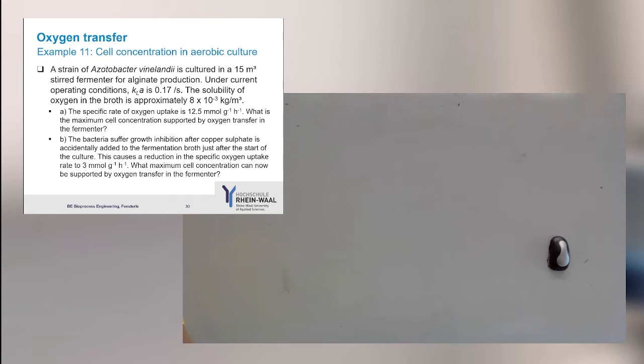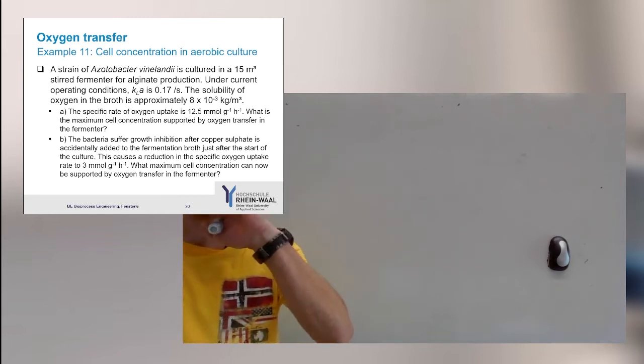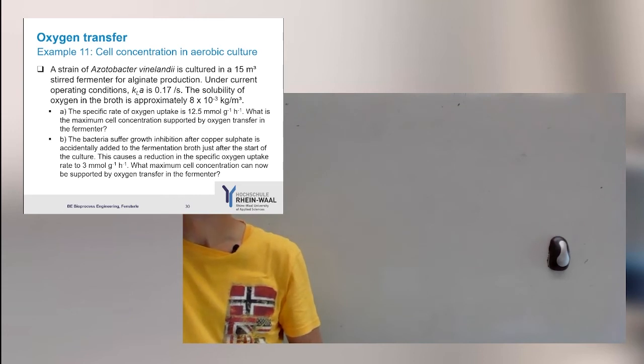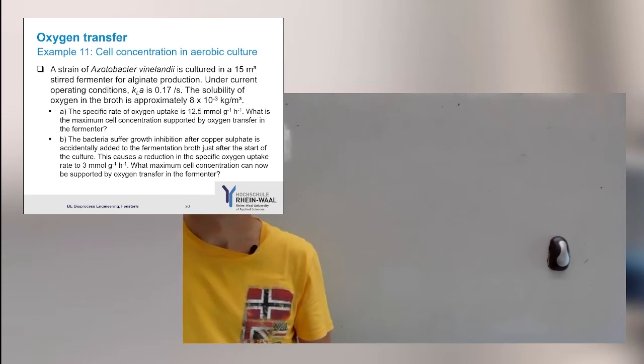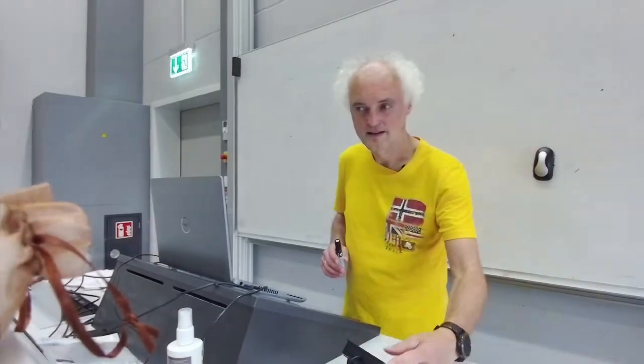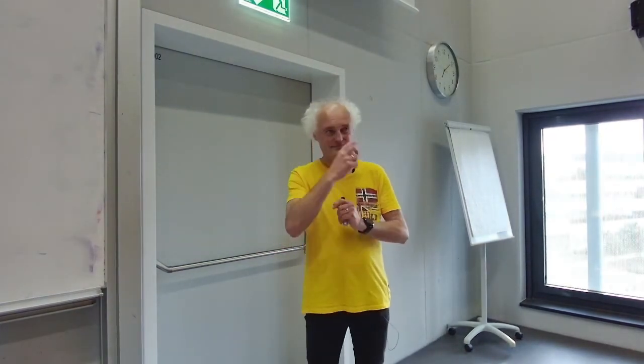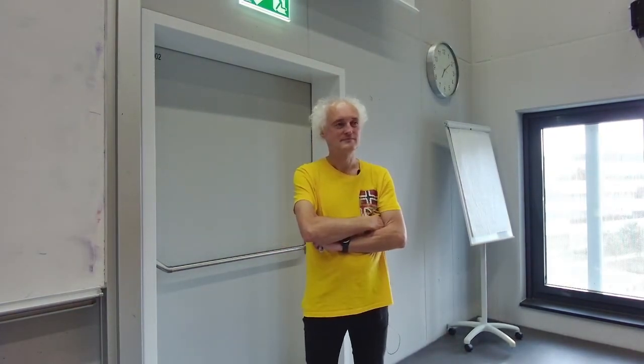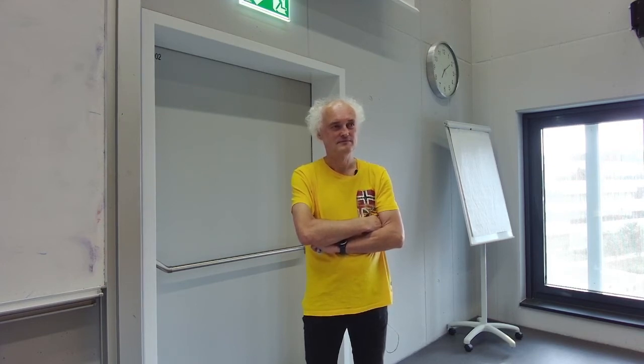Solubility of oxygen changes based on whatever, like water or broth or honey. It changes based on this, right? So for every different substrate, you're going to have to calculate the oxygen solubility, given you're working in aerobic conditions. Say you have a specific broth of your own making, you're going to have to calculate the oxygen solubility for that broth if you want to get the maximum cell concentration.